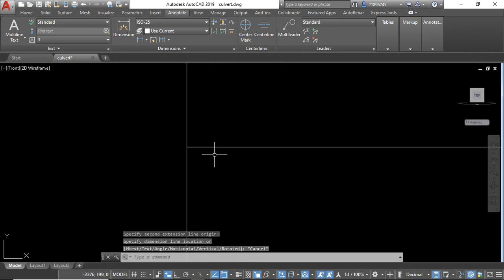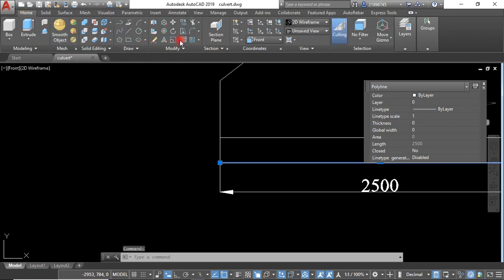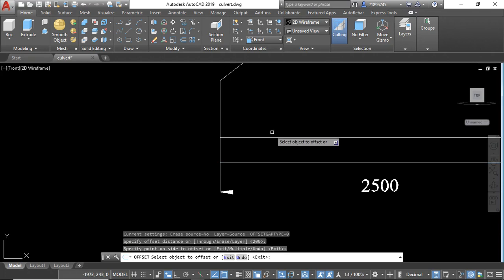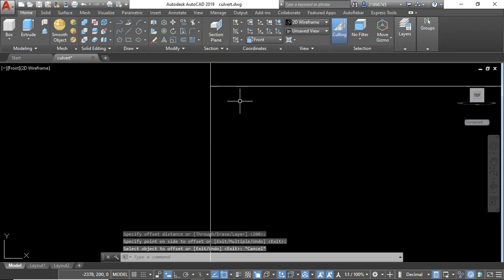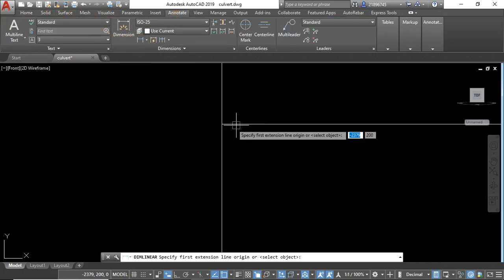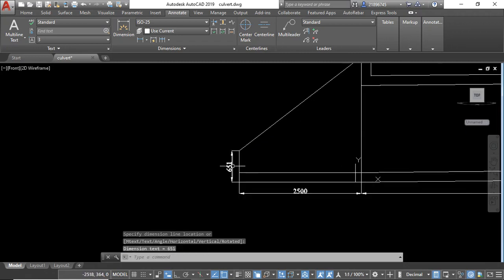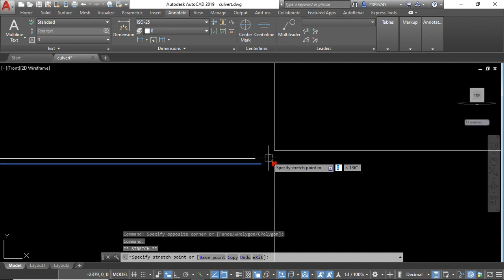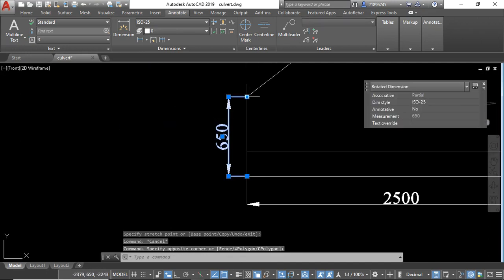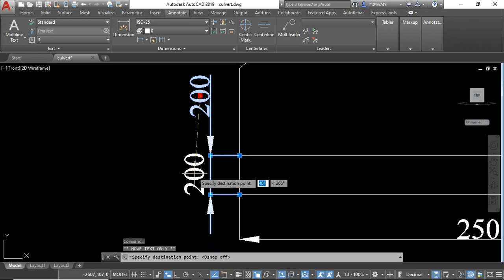I don't know why we are having a weird figure here. Because I want this one to be 200, let's see if I offset how much I get. Same point. So if I go back to the annotate, I can see if everything is correct, but it's still giving 201, and that is just 1 millimeter. I see where the issue is. The issue is where I was picking the endpoint. Now, okay, this is okay, so I just place my cursor here and select this, then I click off the snap.